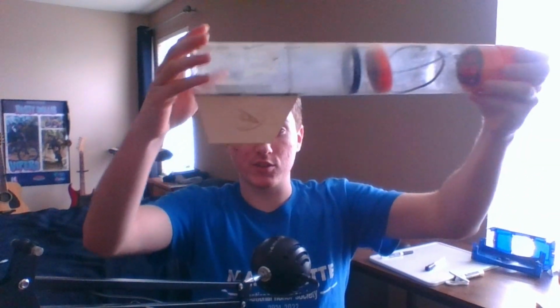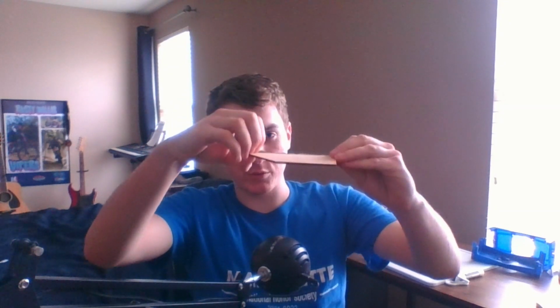So projected surface area, what is that? I am holding a fin right here. So you can see how many pixels it takes up on your screen. It's about that big. But you notice how as I rotate it, it appears to get smaller. It's not getting smaller, but there's less surface area exposed from your perspective. This is projected surface area. It's basically area from a perspective, and that's what's important for drag.